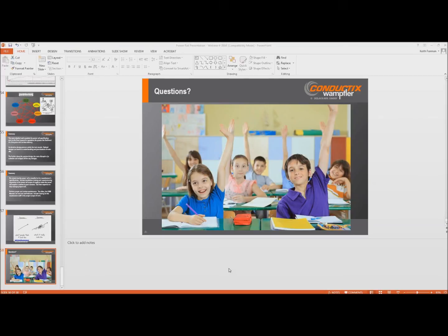Generally speaking, though, let's say a shoe that is 150 millimeters, then we want our gaps to be less than 75, probably closer to a third of the length of the shoe. So for a 150 millimeter length shoe, it's ideal to have the gap somewhere in the order of 50 millimeters. But these are kind of general rules of thumb. As far as spacing between phases,